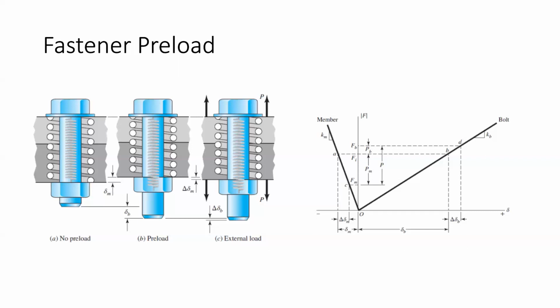But basically, when you have these fastener interfaces, generally the larger your fastener and the larger the mating thread, the larger the strength of it is going to be, right? That makes sense. So that's one parameter. And then you also have the relative materials of the mating thread and the fastener. But another consideration is also the threads and how they're distributed. So in general, if you have smaller, finer threads, but you have more of them, they're going to distribute the load better than larger threads.